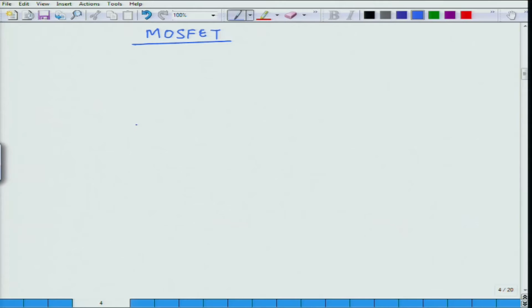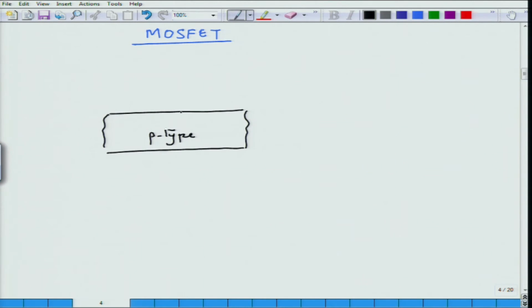So, what did we do there? We had a semiconductor. Let us say in this particular case also I take a p type semiconductor. On top of that semiconductor, I have oxide, and I am making contact through the metal on top. So, on this is making the metal contact, and here I was applying a voltage. In case of capacitor, here the voltage applied we call the gate voltage with respect to a reference, which we will define little later. And the p type semiconductor is also contacted, where we apply the bias with respect to the device here and see what